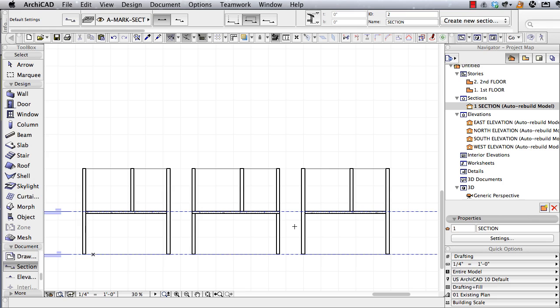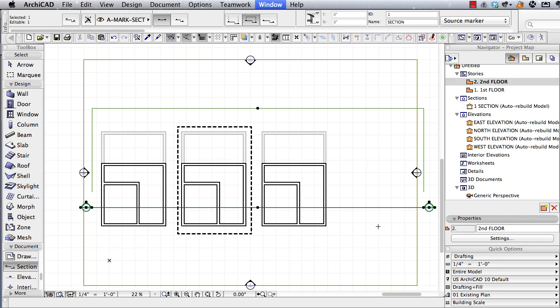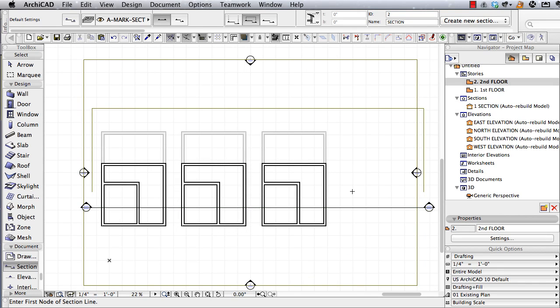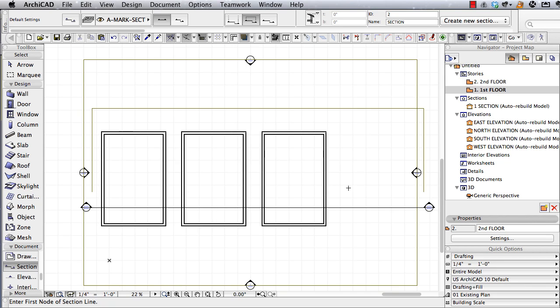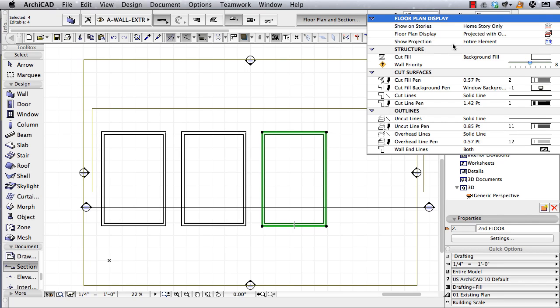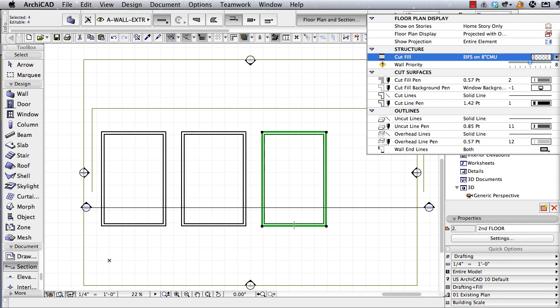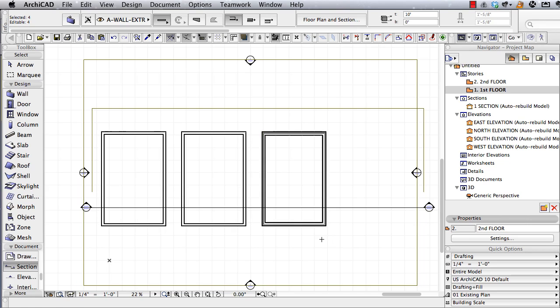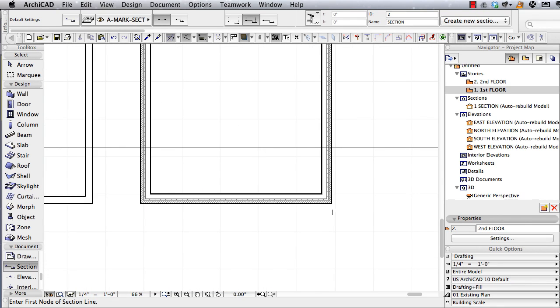And as we start to do that, we might want to think about creating these walls with more detail, actually having them with composites as well. So let me go here on the floor plan, and we'll start on the lower story, and I'll go ahead and select these 4 walls here and choose, in this case, instead of just a simple fill, something that has more detail. So you can see how I've added a lot more information